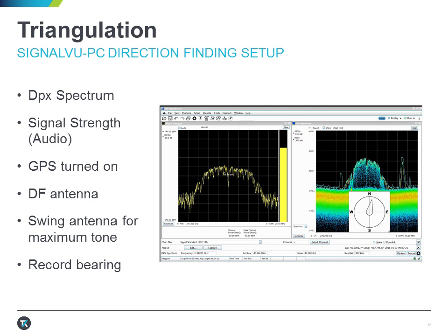This is a big problem in dense urban environments where we have multiple frequency assignments. It's much more difficult to determine what type of frequency or spectrum we're looking at if the only thing we're looking at is a basic spectrum display. The DPX spectrum or RF persistence spectrum is going to give us an idea whether we're looking at a co-channel problem or an interstitial problem, and if we're measuring the right problem at the right time.